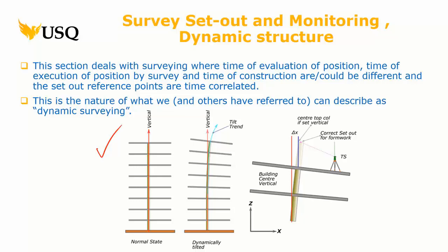It doesn't happen. So this was their problem, because once the building got to a certain point, and I don't know if I mentioned this before, there's a critical point at which your traditional surveying goes out the window. For high-rise, it's about 150 to 200 metres. Not for every single case, but you start to get to the point where you can't have control, because you're not going to be able to see everything. Your vertical plumbing starts to lose out, the precision starts to fall apart. You have to come up with something different.